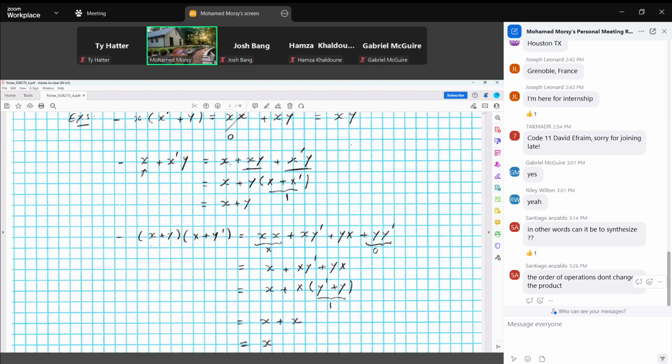So here, when we put X in this form, X plus XY, this is actually equal to X, as we mentioned in the properties. A plus AB equals A. So this is X plus XY. But the purpose to do that, as we mentioned, is to simplify the expression. Because when we put this and we add X inverted Y, now we can take Y common. So it will be multiplied by X plus X inverted. And we know this term is 1. So Y times 1 is Y. So this is equal to X plus Y.